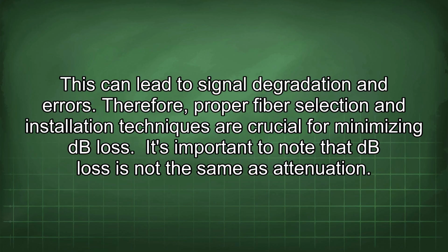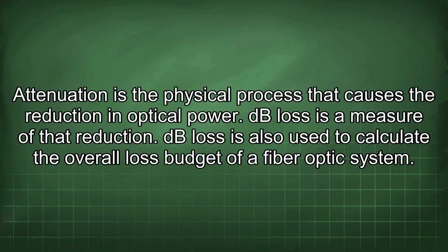It's important to note that dB loss is not the same as attenuation. Attenuation is the physical process that causes the reduction in optical power. dB loss is a measure of that reduction.